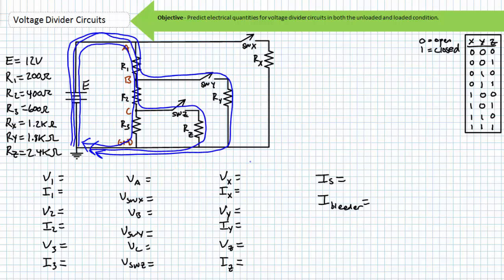When both switch Z and switch Y are closed, Rz is placed in parallel with R3, something I'll call R'. R' is in series with R2, something I'll call R''. Source current will travel through R1, and at node B, current bound for load resistor Ry parts ways with that current bound for R''.